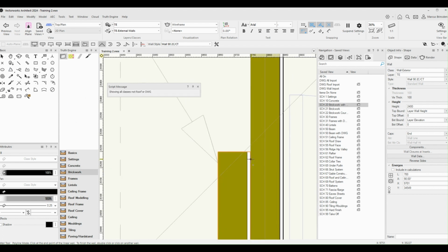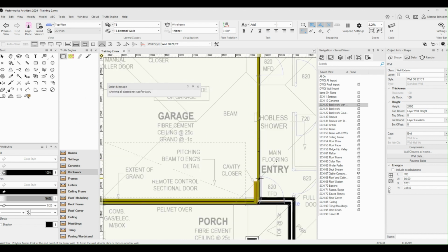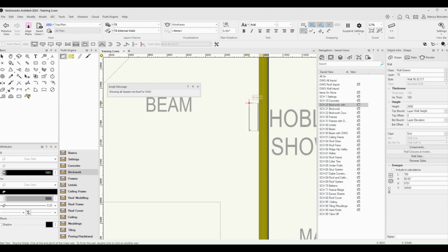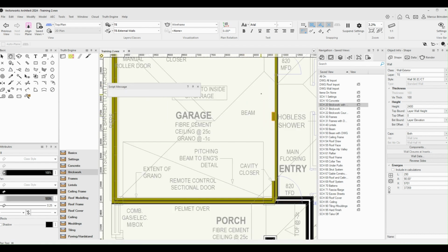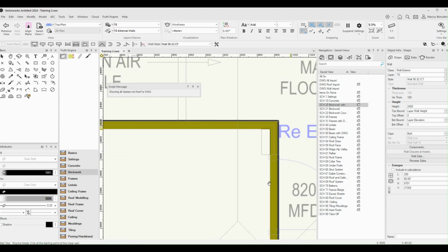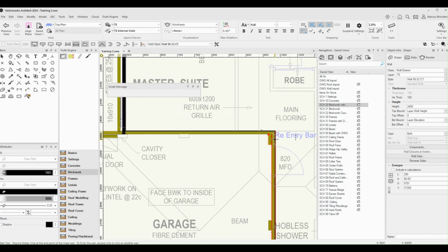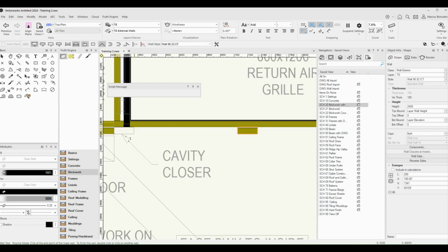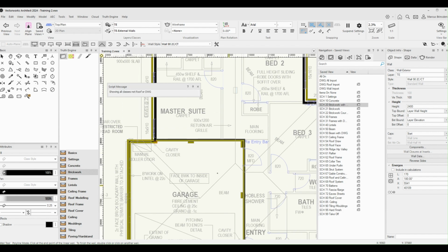It does all the intersection for you. The intersections are pretty good in Vectorworks, but there's our cavity ties component, and then we'll just go around. And of course these walls are defaulted to be at -2 courses, so they'll be sitting on the footing already. There we have it.